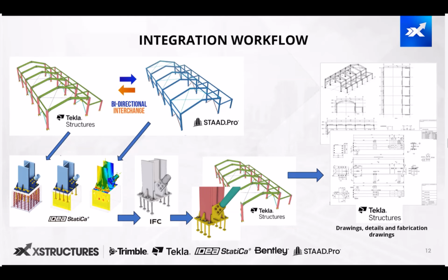Then from IDEA Statica to IFC, designed and verified connections are exported via IFC, or what we call the Industry Foundation Classes, ensuring standardized, open data exchange. Then IFC to TEKLA. The IFC file is re-imported to TEKLA Structures, where the constructible model is updated with verified connection details and fabrication-ready information. And then finally, the TEKLA model will be the final model to produce drawings, details, and fabrication drawings.